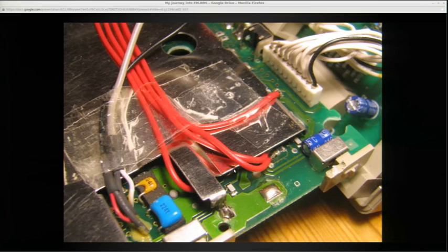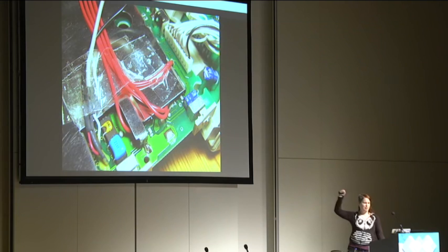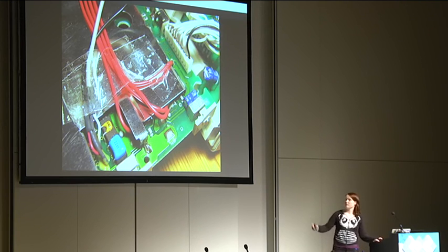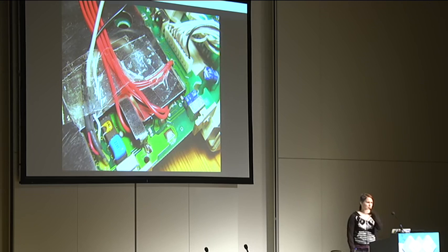And then I used my sound card to sample that, because it so happens that the voltages the sound card is using are very close to the logic voltages of general ICs in the 1 to 3.3 volt range. So I actually used a sound card to sample the logic coming out of there. And it's 1 kilobaud, so it's not even very fast.